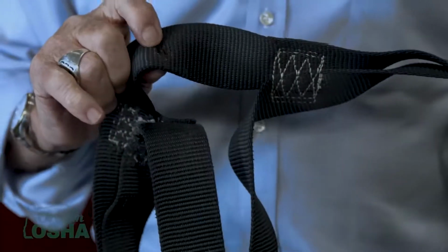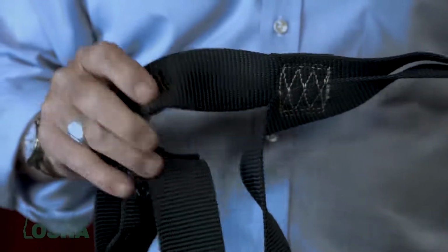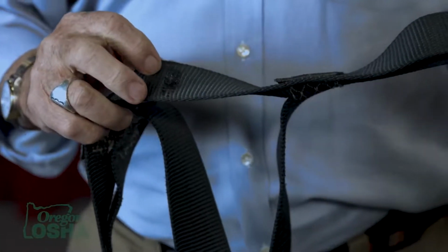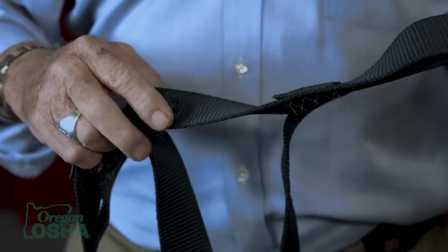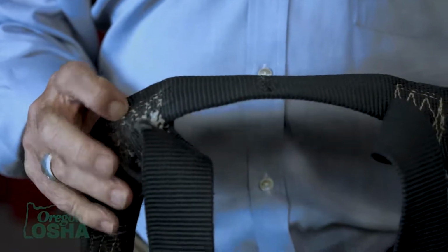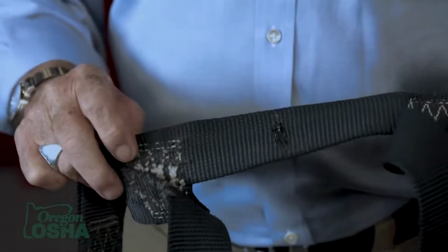This is an area that's subject to a lot of abuse, particularly around heat. We weld something, we throw bricks against it, next thing you know, we've literally welded our harness. Material doesn't function well once it's welded on or gets heat. It melts, it gets brittle, and that's a real problem. You want to look at your stitching. So when you look at your stitching, make sure that you turn it over and compare.